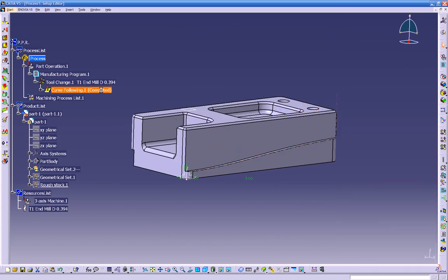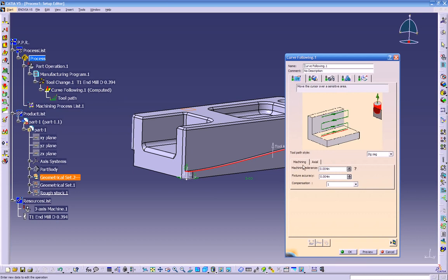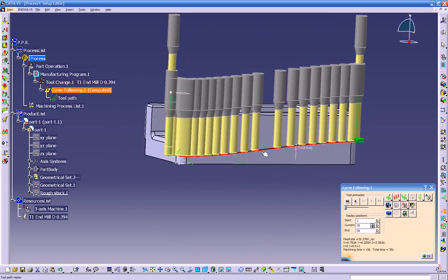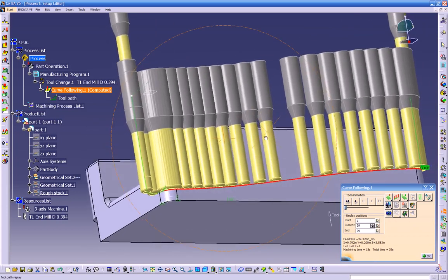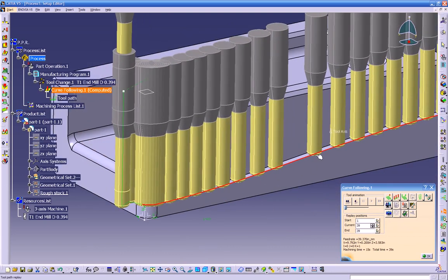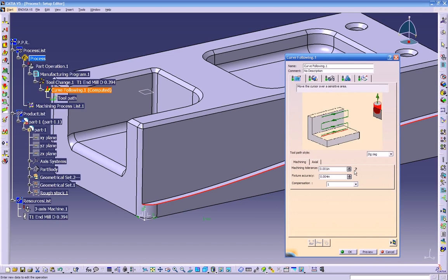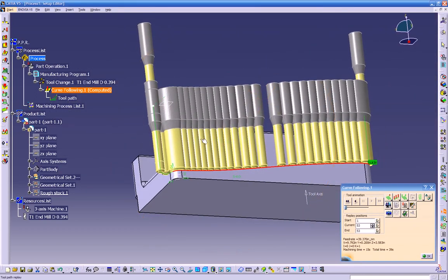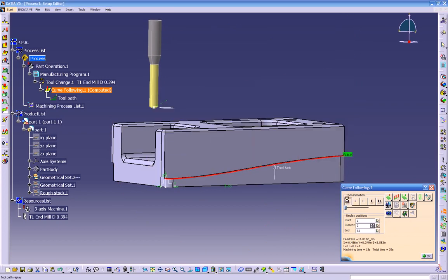And we go back into the operation, double click here, and over here on the tolerance, if we decrease this, let's change it to 1000. Look at the difference. See the tools, we get more tools, so our tolerance is better. So if you want to have a nice finish on the part, that's the place you come and change it. So even show you right here, it's a tolerance. So the smaller you make it, the bigger the program gets, but the finish of the part is going to look so much better. So look at the difference, how many tools we have, all these positions.